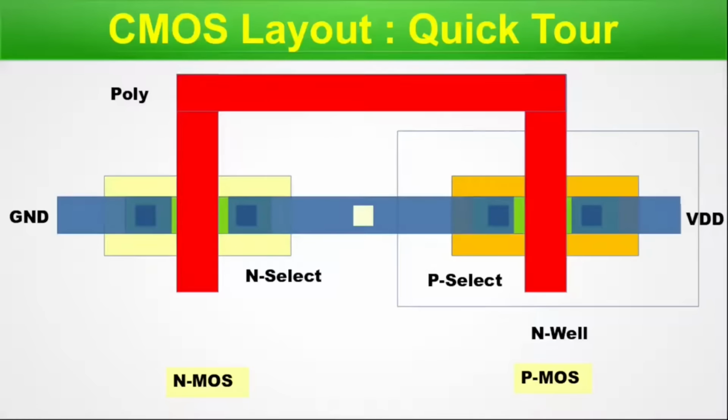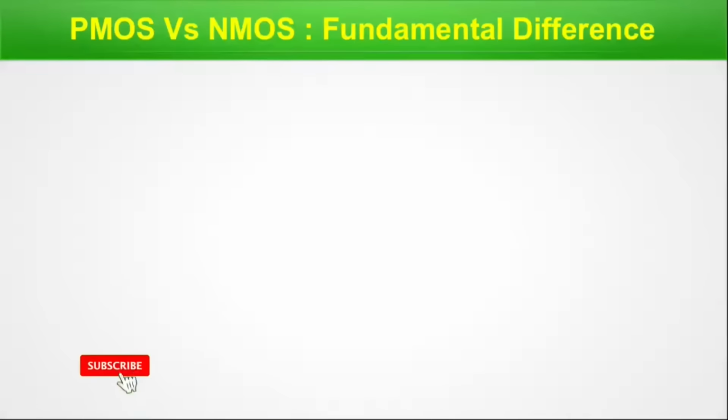And the reason why I have shown you that here is the process corners mostly depend upon two terms, one belonging to NMOS and another belonging to the PMOS. However, at the very basic level, when you are asked in an interview, you may be asked this question: what is the basic difference of NMOS versus PMOS? I'll come to the details. Here, let us go through the graphical representation. Now, generally, we make the area of the PMOS twice the NMOS area. We'll come to the reasons in the next slide. We are done with this particular slide, so let's move on.